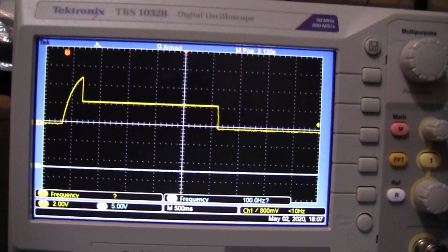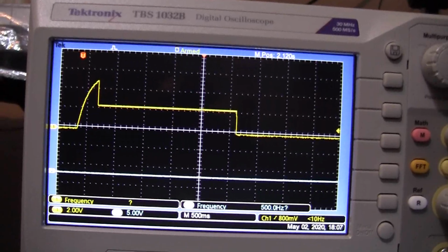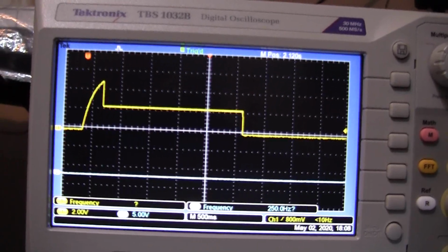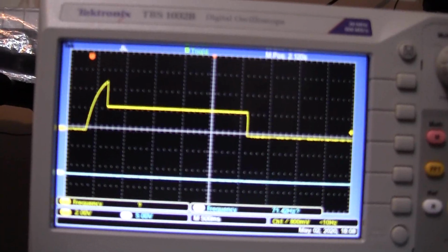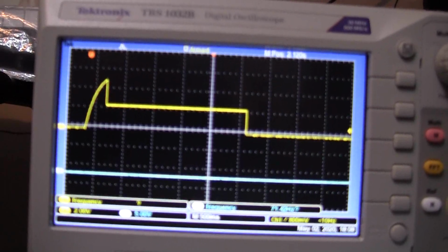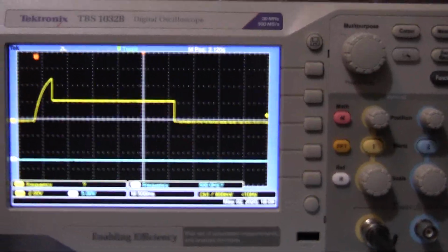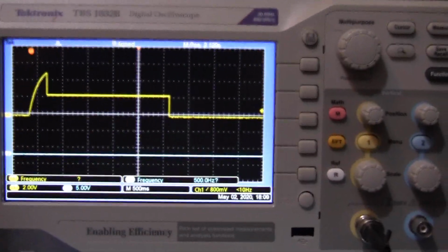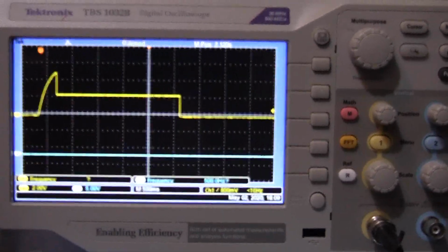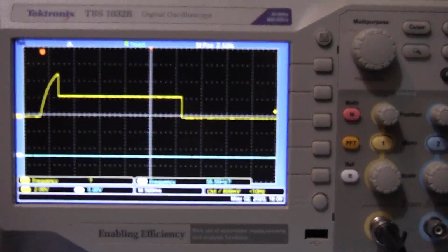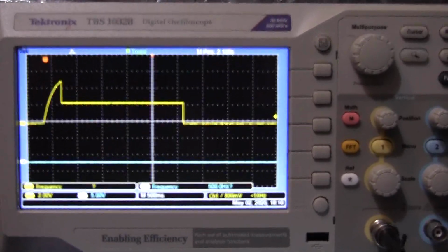Now on the oscilloscope, what we're seeing is consistent with what we have. Notice that we have the complete fall off there after the sustain period down to 0, and we have a curve coming from 0 up to the maximum with absolutely no decay, dropping back down to the sustain level. The Q109 is not going to have straight lines for the attack and the decay and the release times, because it depends upon the charging and the discharging of the capacitors.